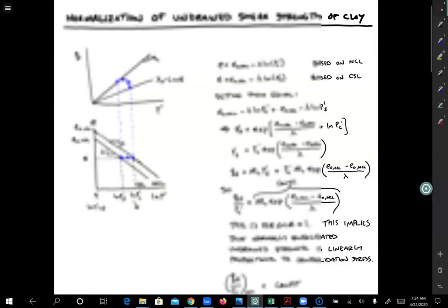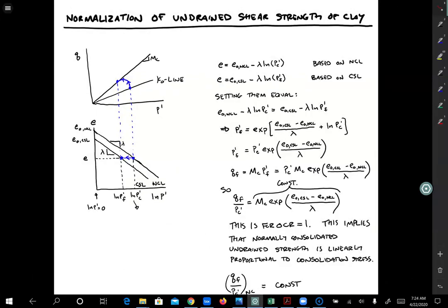Okay, in this video I'm going to talk about a really important behavior of the undrained strength of clay, and it's normalization of the undrained strength with vertical effective stress, or alternatively P prime, and OCR. So if we know P prime and OCR and we know the position of the normal consolidation line and critical state line, we can actually calculate the shear strength based on those properties.